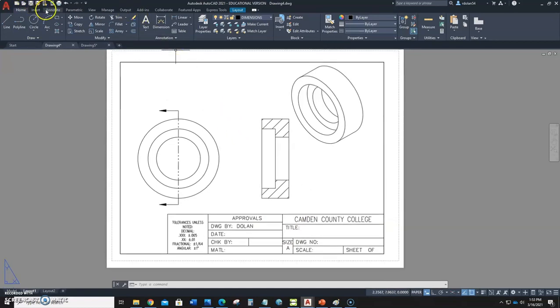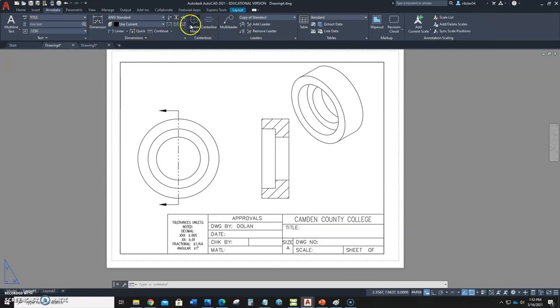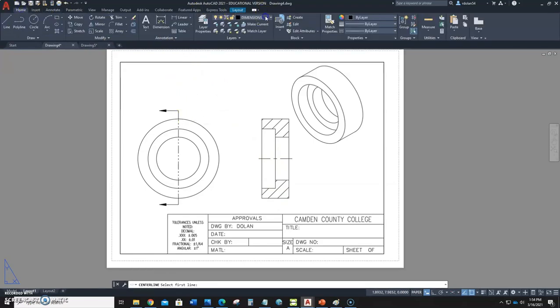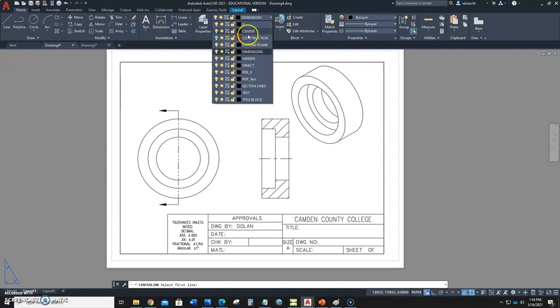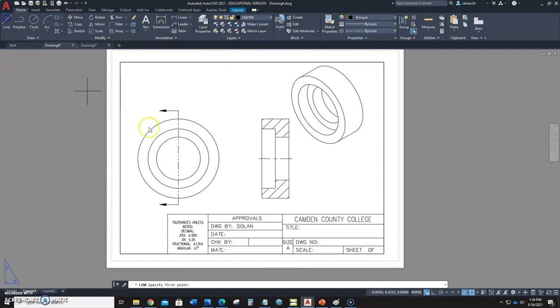Okay, also don't forget, while you're here, I can go to annotate, and I can put some center lines in here. I'll want to go from here to here and have a center line. I'll also want to make a center line. Let's just go here. Let's go to center line. Somewhere center. And I'm going to go from maybe the quadrant here, just add a little bit. Then across here to the quadrant. Put F8 on. Quadrant just a little bit past it. Okay. And there we should be good. Okay, hopefully that will help.